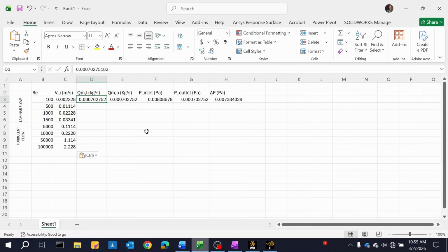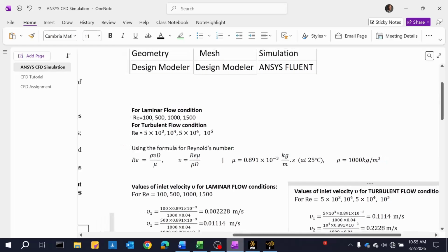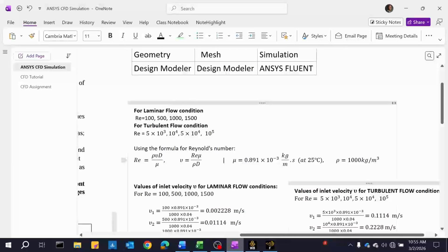You're going to write a technical report with your introduction, governing equations, the Fluent setup, your assumptions for the system. For example, in this simulation, I assumed that the dynamic viscosity is this value at this temperature. So I assumed that the experiment was run at 25 degrees Celsius.